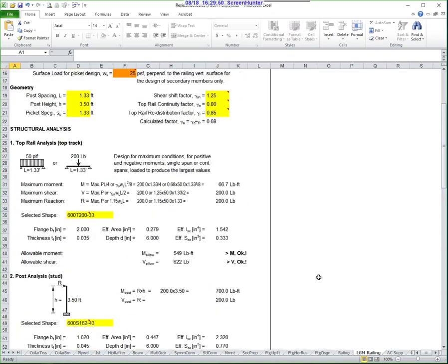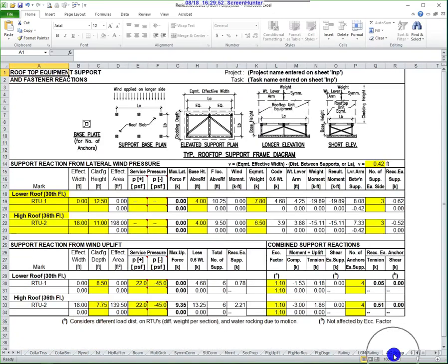AC SUP, for design of rooftop unit support frames. This worksheet applies to the design of frames supported by rooftop equipment units, consisting of short columns with beams on top. This type of frame is called in some places as dunnage or trestle. This program calculates reactions only plus the number of anchor bolts required at the bottom of legs, short columns.